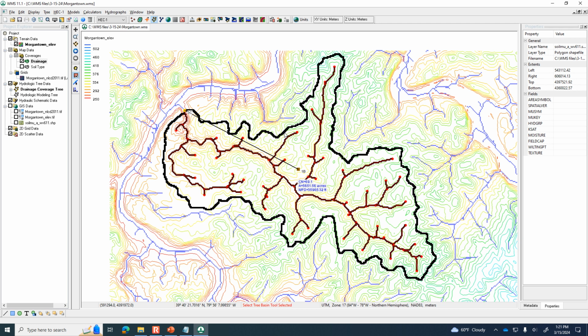So it would be like the flattest path you could find around the perimeter of the watershed if you stayed on the ridge line. Now, not everywhere here has the same elevation, so this black line isn't all the same elevation, but it's going to be much less elevation difference along that black line than if you were to cross down towards the creek. Then you'd go through big changes in elevation.